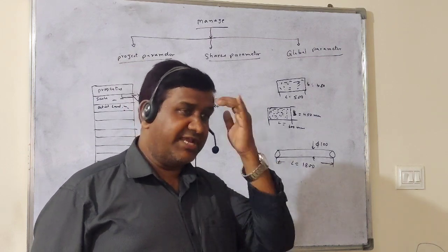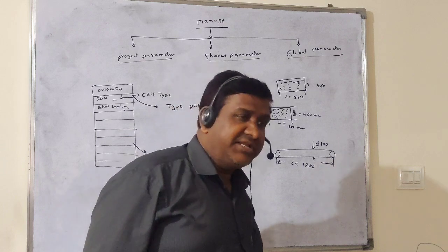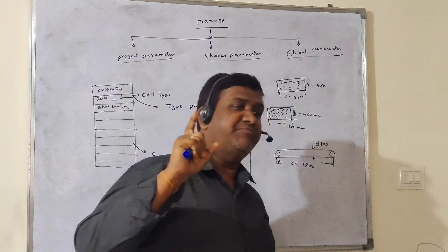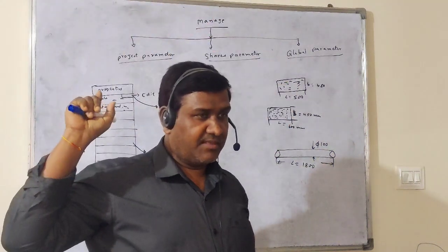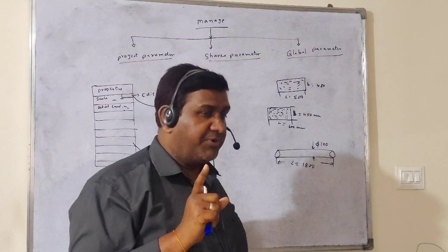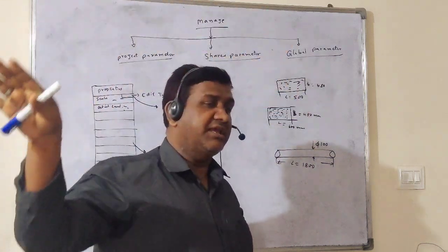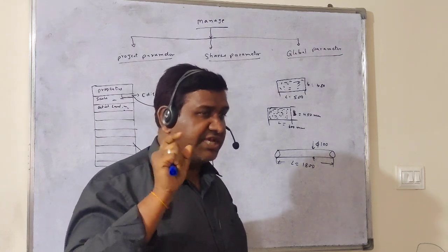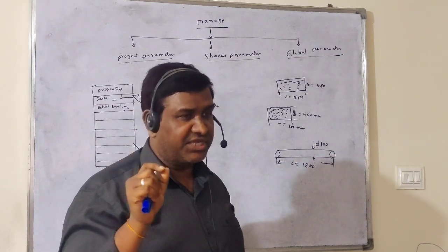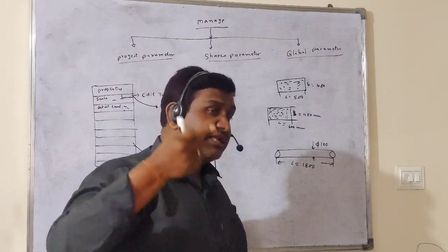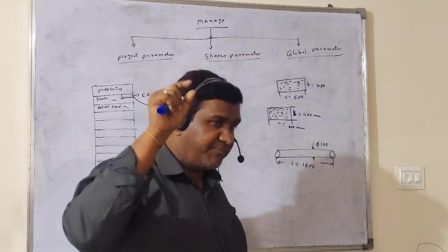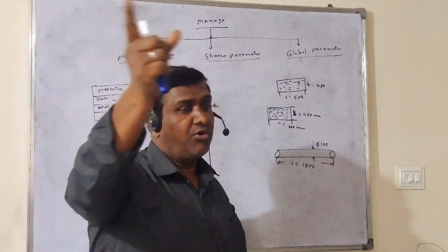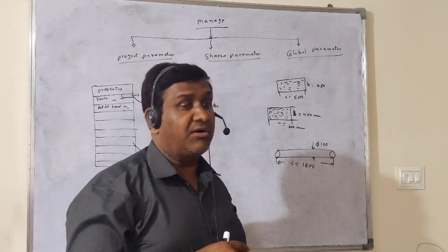In simple language, if you change any parameter of a component, and that component has been placed in many places, remember, if any component which you have placed in multiple areas, with the same name, and you want to change something like sizes or some information in the edit type parameters, the type tool palette, then it is going to be changed in the whole area wherever you have placed the component.